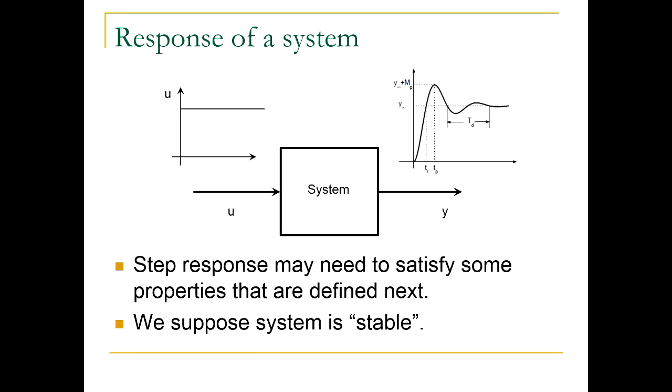All right, so here is a typical test that we do in control systems to define what we mean by transients. Suppose that your system was at rest, at some equilibrium. And then you apply to this system a step input. This signal was 0 up to time 0, and then it's some constant, let's say 1, for positive time.